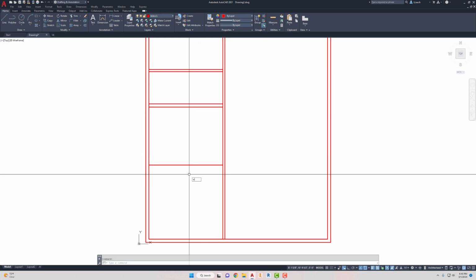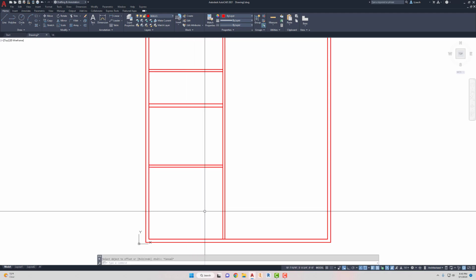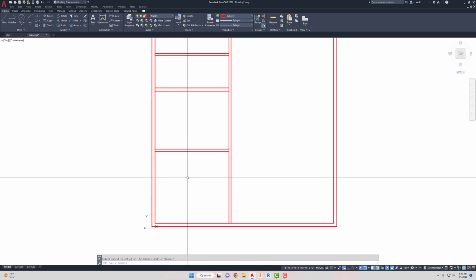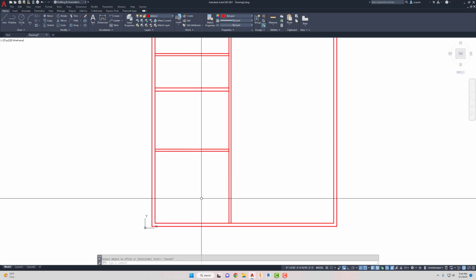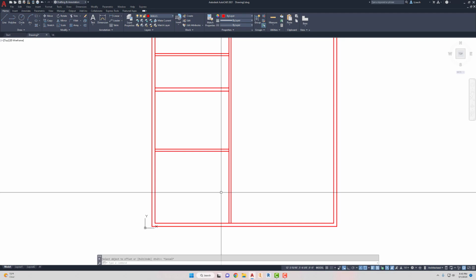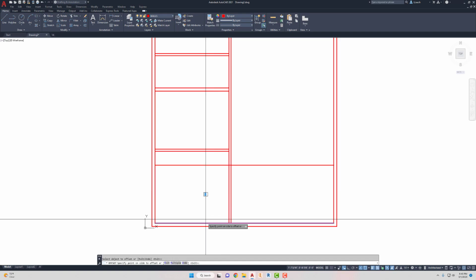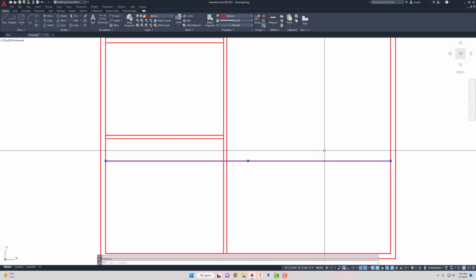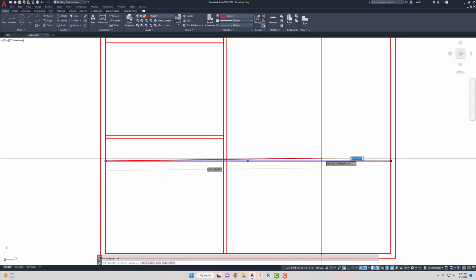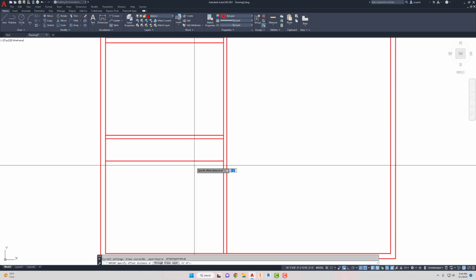Down, offset that 4. It doesn't say what the closet dimension is, so I'm gonna offset this line up because it does give us the dimension for that bedroom. So that's 9 feet. So offset 9 feet. This one up. Again, let me do something different. I'm just gonna grab this and drag it over instead of trimming it twice. Then I'm going to offset that 4.